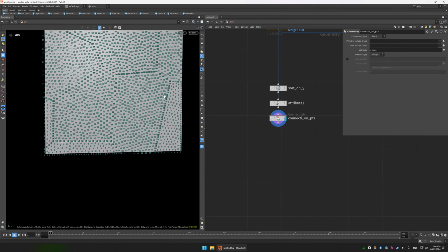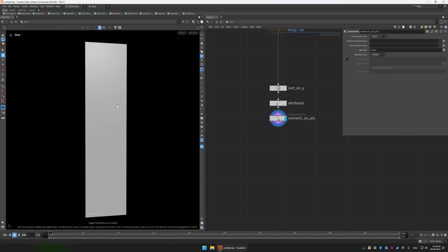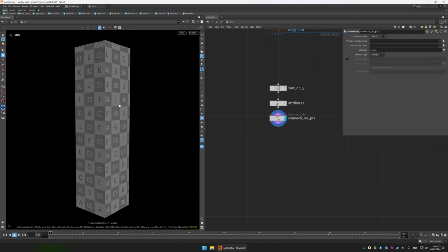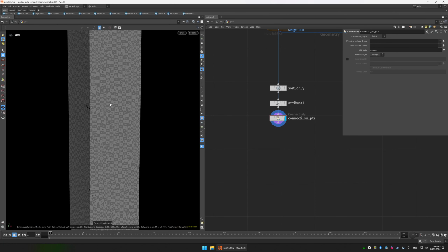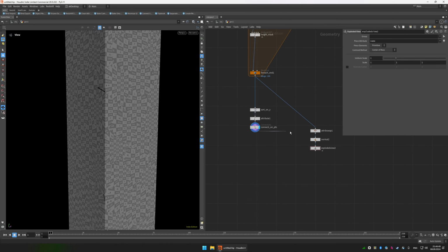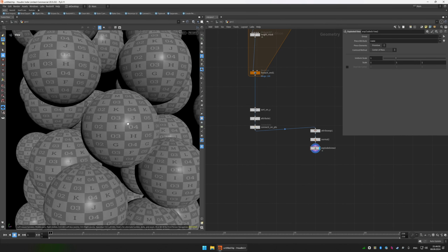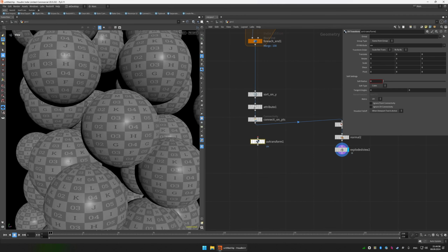Okay, and now I'm also going to quickly fix a problem with the UVs. So if you visualize this UVs, this is our first UV, but if you press space 5 in the UV view mode, you can set this to UV2, and then as you can see, if we visualize this like this, those are a little bit stretched, so we can use UV transform here.